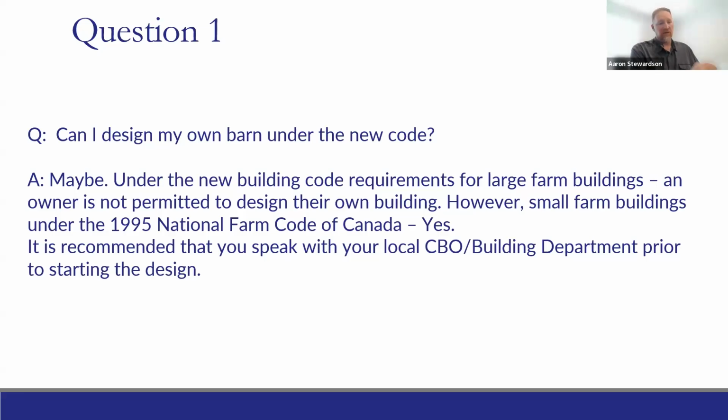So you can do it under the National Farm Building Code using SB 11, and all of your seismic, your snow loading, your wind loading all reverts back to the 1997 Ontario Building Code. But like I said, before you start any design work, have that discussion with your local CBO. We're not as scary as you think. Give us a phone call, have a discussion with us, right?